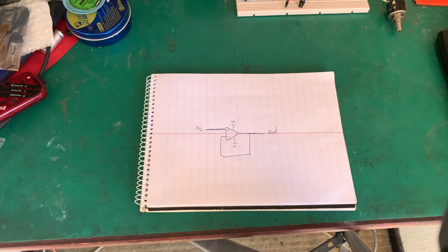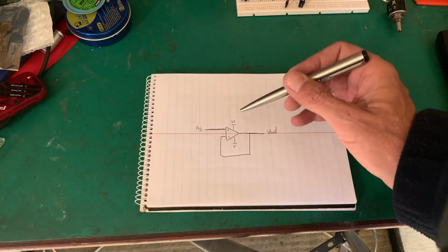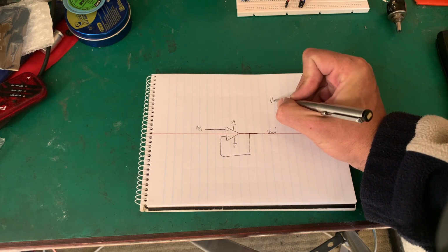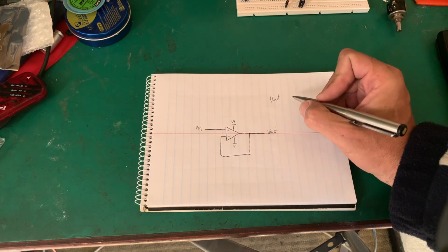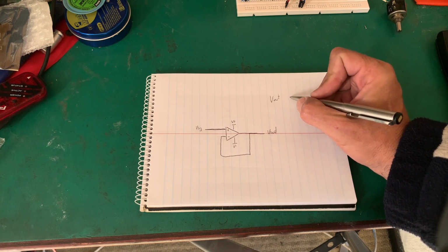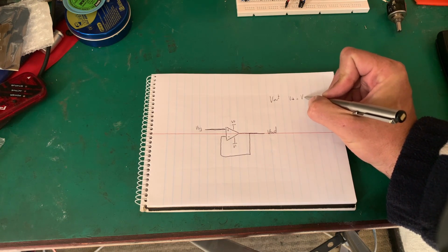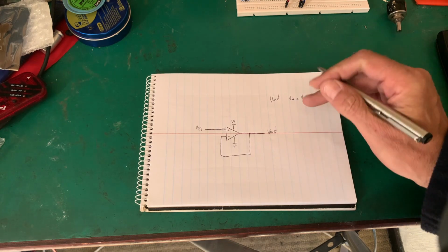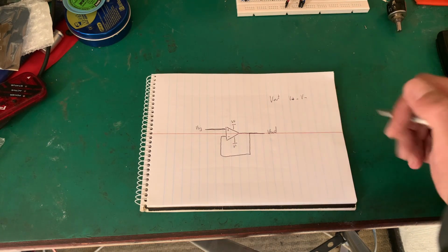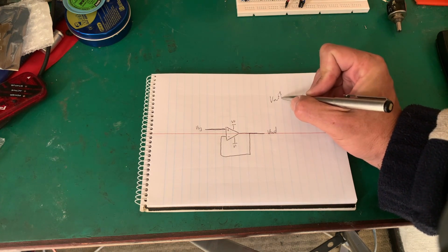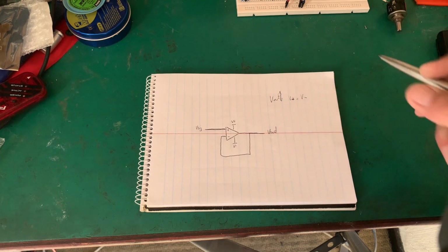Aha! So now this starts making sense as an amplifier, because why? Let's think of that for a moment. So V out is going to do whatever it can to make V in, or V plus, equal V minus. In other words, make the inverting and non-inverting inputs the same. So V out will do whatever it must to achieve that.